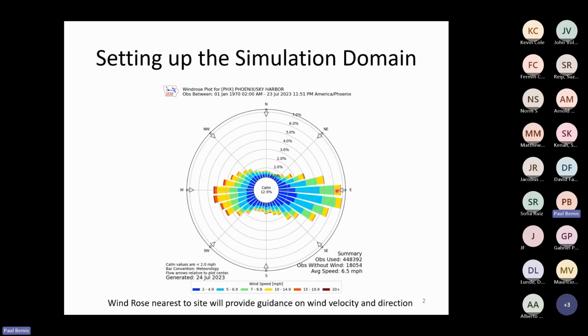A lot of the time I've got a wind that flows from the east, 6-7% of the time. I also have one that flows from the west, 4-5% of the time. My absolute magnitude, the biggest one, is really in the range of 15 to 19 mile an hour wind coming from the west. I should check that one. That's one I should look at in my model. I should also take one from the east and take a look at that at 10 miles an hour.